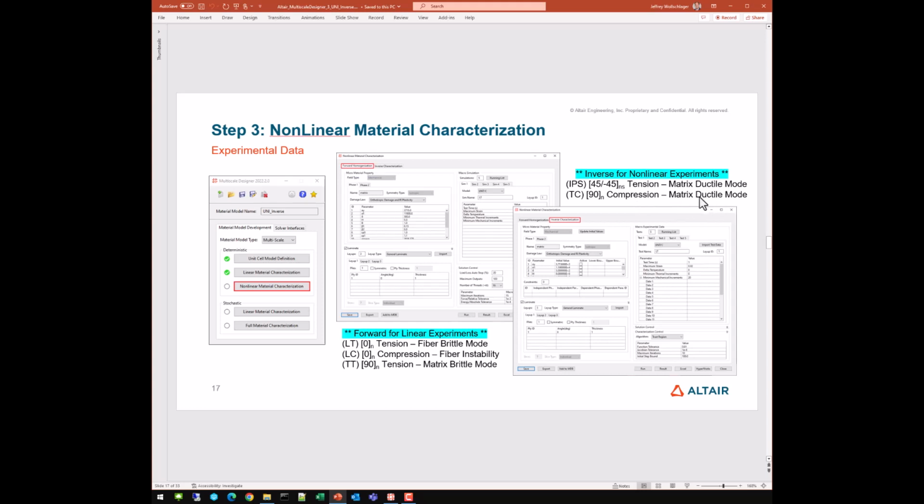If you did have it, you would be able to inverse characterize beta values a little better, because I'd have two specimens at different volumetric strain. So this one at basically a 0 volumetric strain, and this one at a negative volumetric strain, which would allow me to inverse characterize the beta value. Remember, beta was the Drucker-Prager characterization that allowed the yield and tangent stress as a function of the volumetric strain, or as a function of J1.